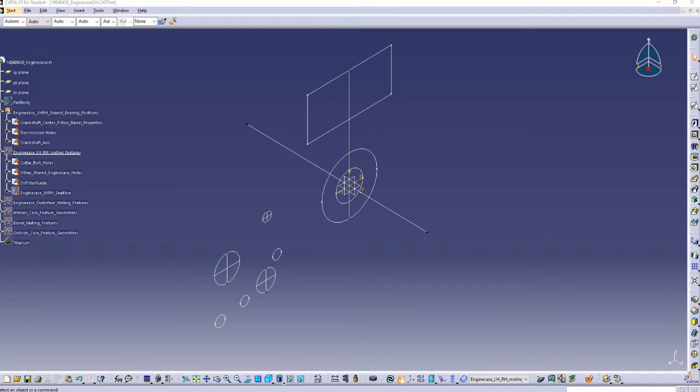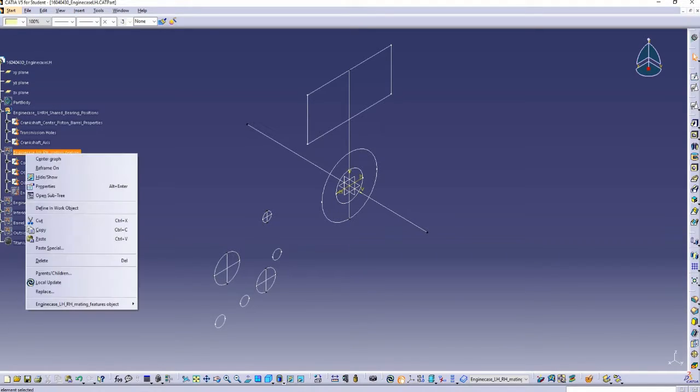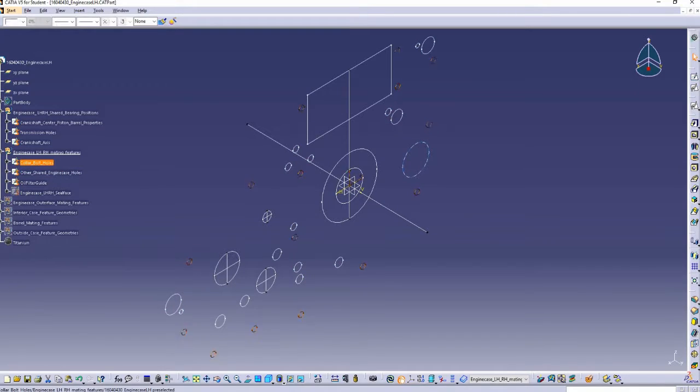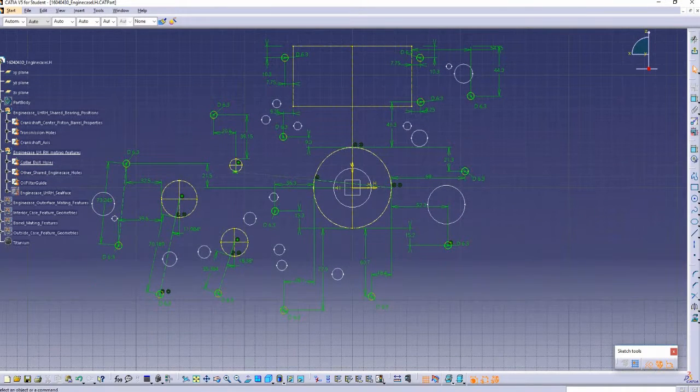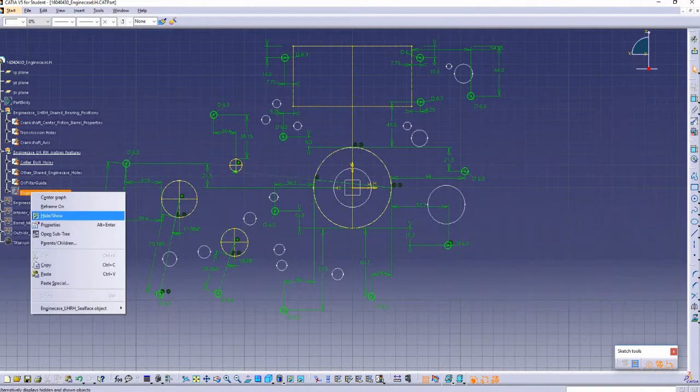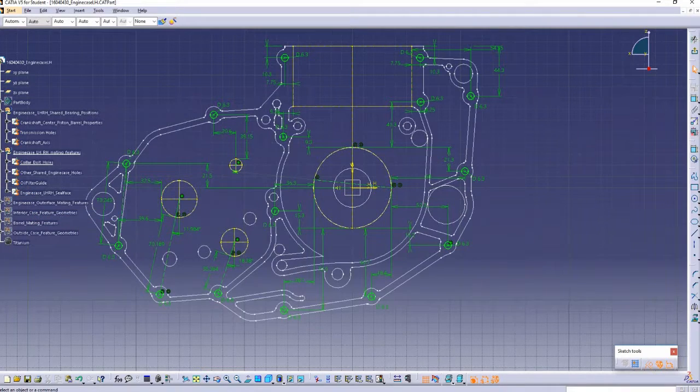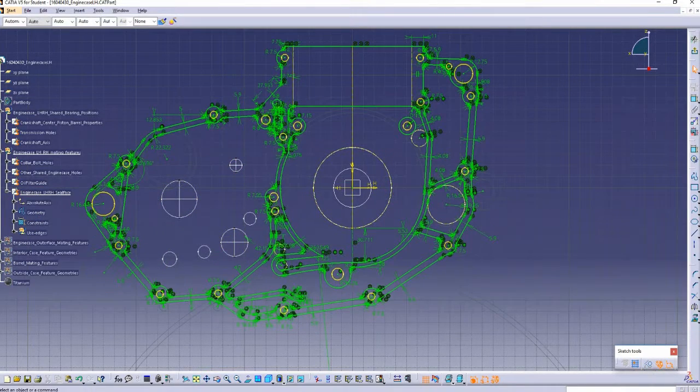Left hand side, as you can see here, I have the crank and the piston geometries as well as the transmission geometries. I'm going to show some of the other key geometries, one being the collar bolt holes, which are all defined off the previously mentioned. These collar bolt holes and the other dimensions drive the engine case, which is another fully constrained sketch I want to show you because the outer part defines the main billet.